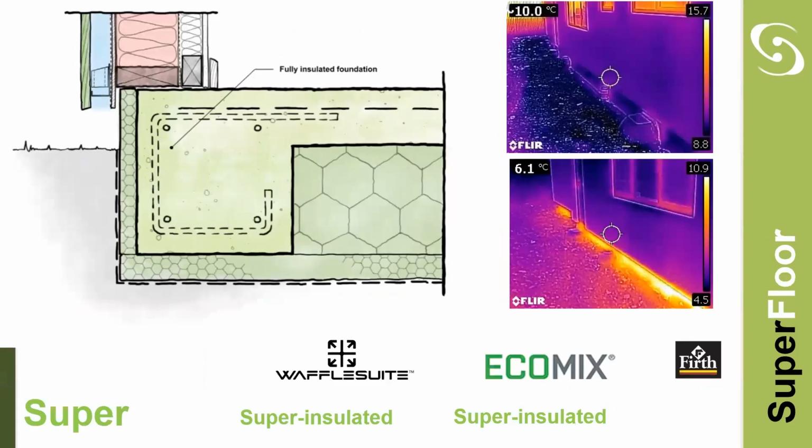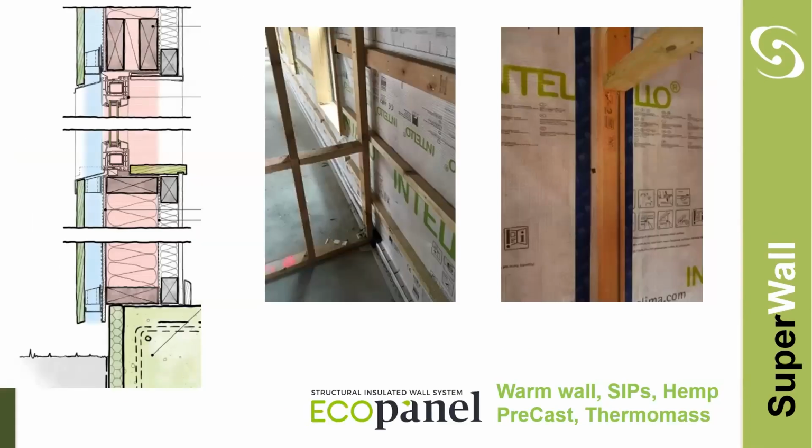If I go back to here, obviously with insulated foundations, we tend to use polystyrene, or EPS, because it is common and it is cheap. But if there were other different products we could substitute in, that would be a great thing. Like for wall claddings, you could go with a cork product. Of course, that's a pricier thing, but that has one of the best R values, and it's a natural product.